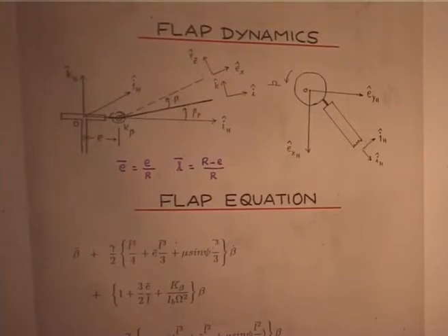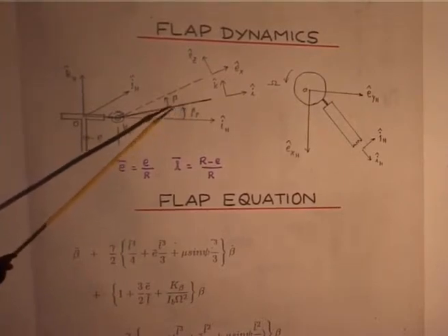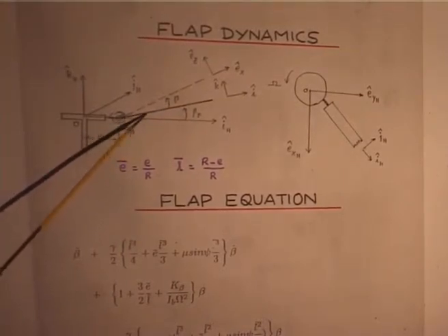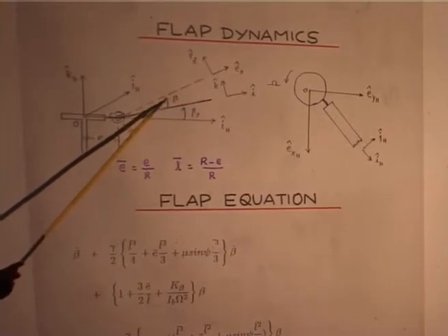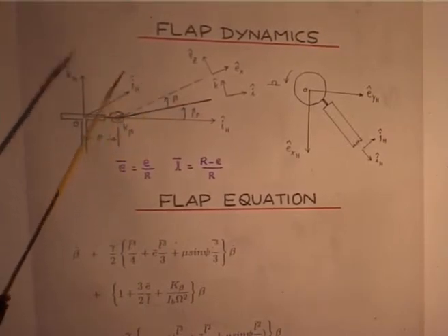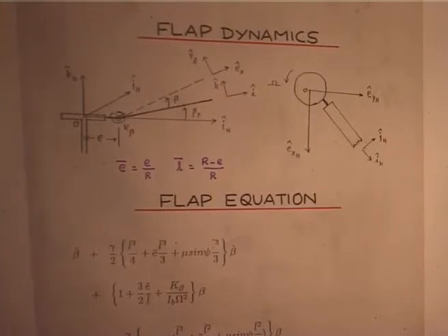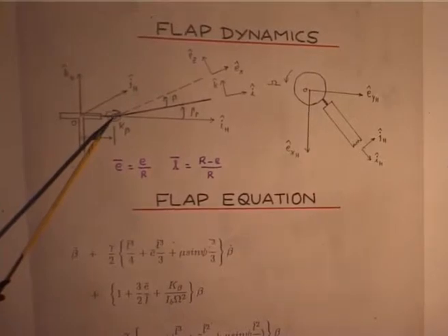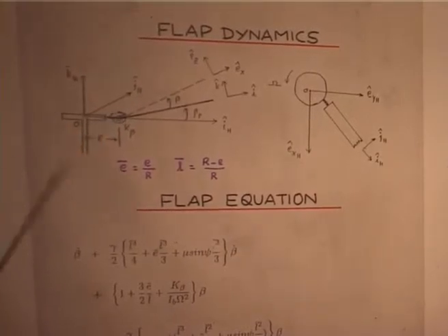Of course, the procedure is identical. I have given a pre-cone, this is the undeformed axis, from there the blade deforms. So, take any point, find out its velocity, find out its acceleration, then take the inertia force, then balance the root moment about this point, because here is the root spring.